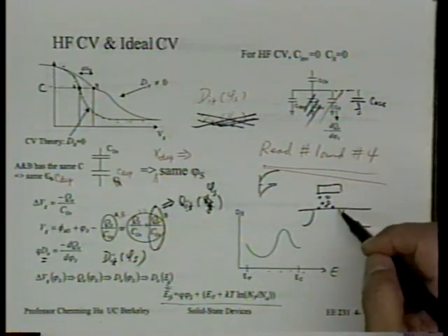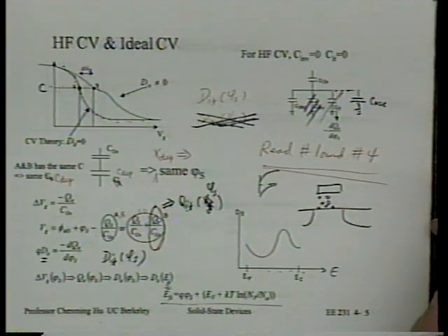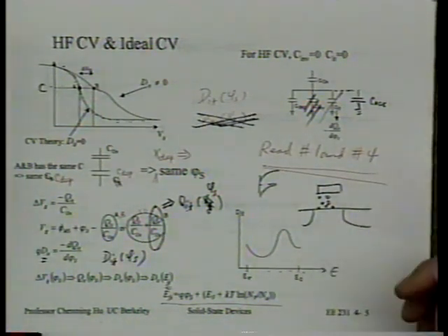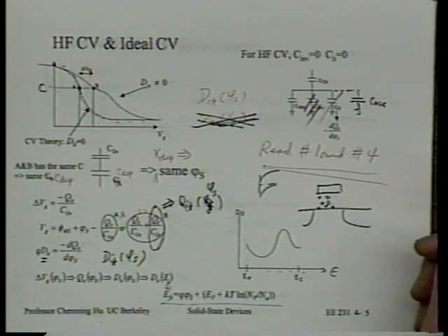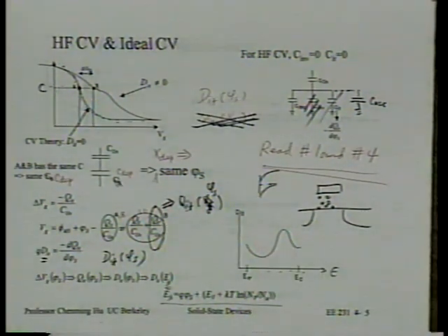Thinking of this SiO2 as an amorphous structure, where can this broken bond be present? It's probably semi-continuous. And indeed, this concept is actually used explicitly to derive some 1/f noise. Later, we may have a chance to mention it. I don't have a lecture plan, but I have a reference for you.